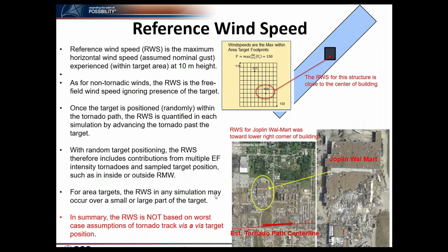One of the important things when you are interpreting the hazard from our developed hazard curve is the reference wind speed. Since the tornado is a very small path area event compared to other extreme, non-tornadic events, it has a lot of variation of the wind speed along the path.